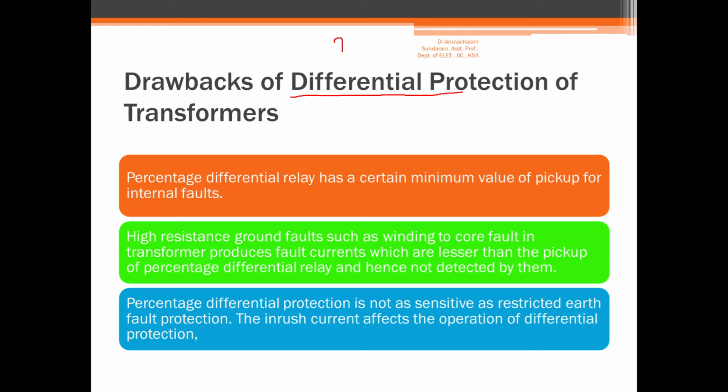at the starting. Why did we use a delay of 2 seconds? Because at the starting there is an inrush current in the transformer, and because of this inrush current the relay will trip. So in order to avoid this, we were using a 2 second delay, and we were also not using 0 amperes as the setting for the current relay. We were using 110% of the no load current, so the sensitivity of the relay was a little bit down.